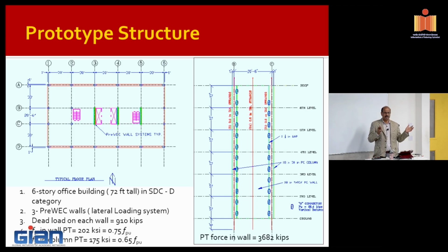So the asymmetry will also come in, even if you design them to be symmetric. The load can excite the building into torsional modes and things like that. So it's not unusual to see. Don't force the structure to be symmetric, because that's not going to respond that way. But you need to pay attention to the fact that the asymmetry will come in, and you have to deal with it. So once you decide that, then you take the frame and do the moment resisting frame.